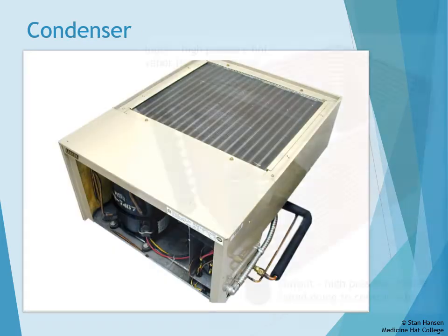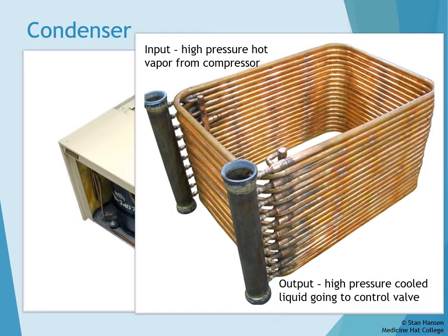The other part of the condenser unit is the condenser coils. These are a finned radiator that is cooled by air passing through, and it is located where the heat is to be discarded, typically outdoors. The compressor will feed the hot vapor into the coils, and then the vapor cools inside the condenser into a liquid state. However, it is still under pressure.